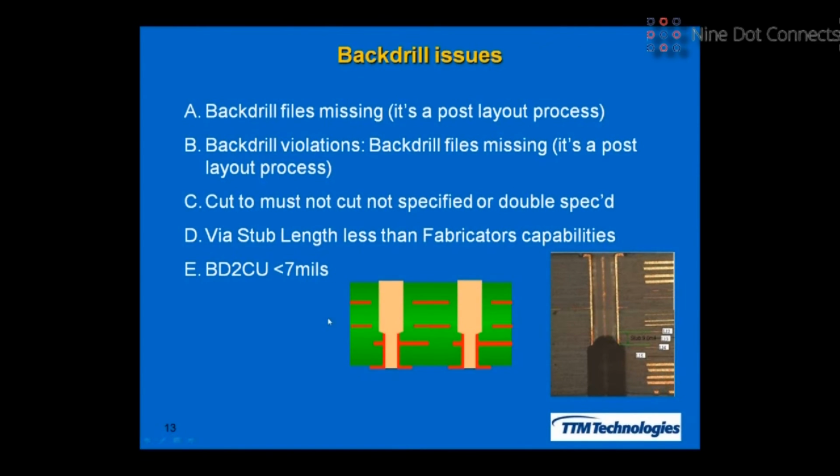Let's see, and then I talked about back drill to copper distance. So that would be like here, this distance right here. It's a big concern. If these planes are closer to this back drill, or they hit the back drill and you have exposed copper, electrically you may not have a problem right now.